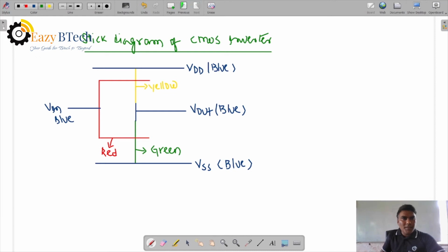And there is a contact area. Contact area, when two layers are interconnected, that is a contact area. Here two layers are there. There is a black contact, metal and the yellow, P plus diffusion and metal. Here also metal and green, N plus diffusion.